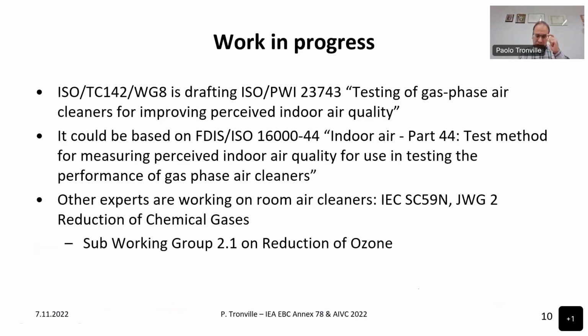So instead of using an instrument to measure the concentration, the purpose is to assess the quality of the air by perception, by a panel of trained people. This could be based on the document listed here, ISO 16000-44, which exactly describes how to perform the measurement of these gas phase contaminants by olfactory tools.